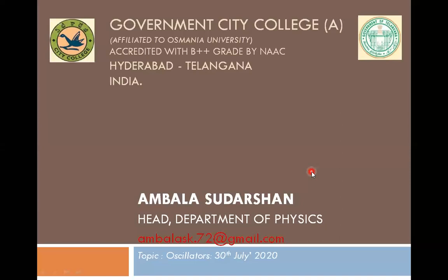We have seen the biasing of transistors also, proper biasing and stabilization. Next, we have seen amplifiers, how a low signal is converted to a high signal. It can be a power signal, voltage signal, or current signal, anything. Especially, we have studied the RC coupled amplifier, resistance-capacitance coupled amplifier. If you want to increase the gain at the output, we can use a cascaded manner. The output of the first amplifier is given as input to the second amplifier through the coupling capacitor CC, so that the ultimate gain will be high according to our specifications.